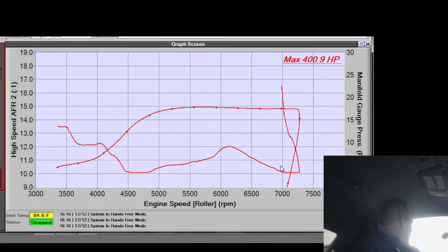Smoothing on. Look how flat that graph is. Yeah, I wish this dyno doesn't have smoothing. It just doesn't have that. Good, they shouldn't. I agree. And when things are bad, boy, it shows. But it looks really smooth now. I mean, but that FA torque dip that they all talk about is gnarly. Yeah, you see it big time. It's like a flat down and then an arc back up.